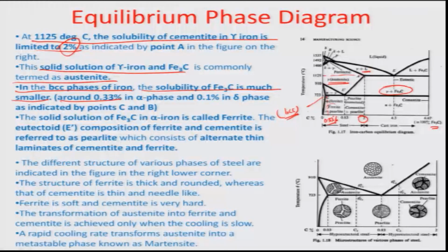As you can see, this particular zone is ferrite and pearlite, and if it goes beyond a certain point, 0.83, it again starts forming cementite and pearlite rather than ferrite and pearlite. Pearlite, remember, is the eutectoid two-phase system of ferrite and cementite distributed throughout the structure homogeneously.